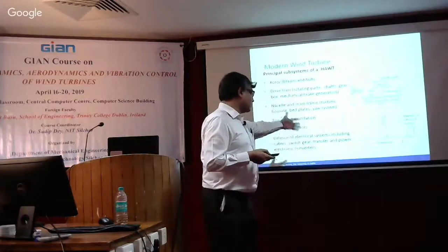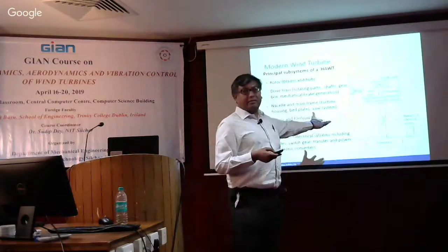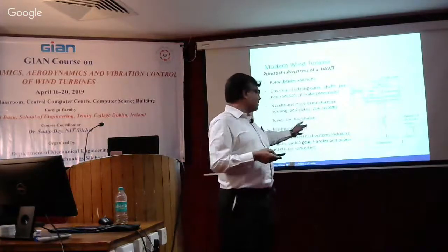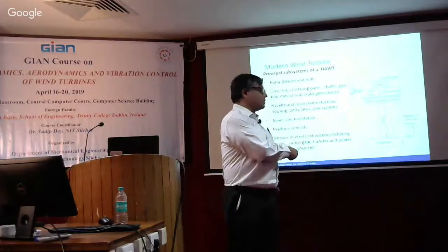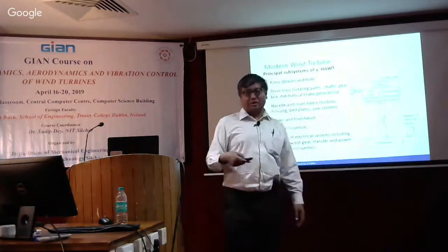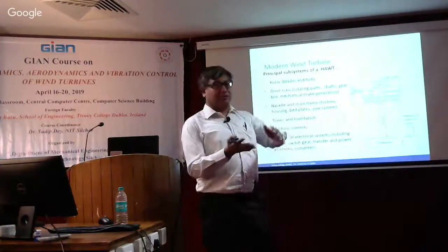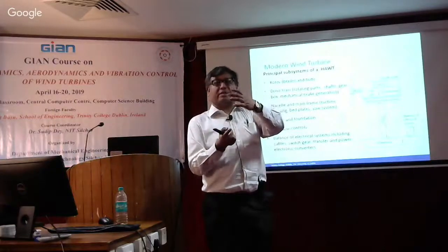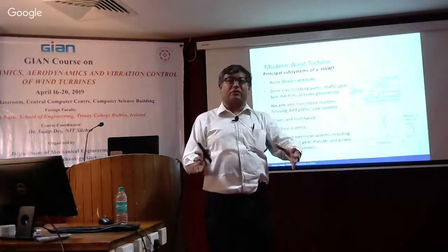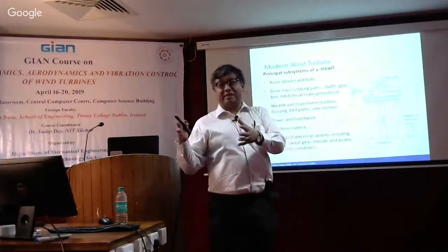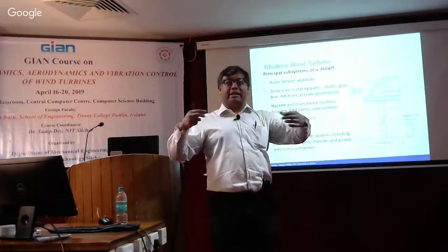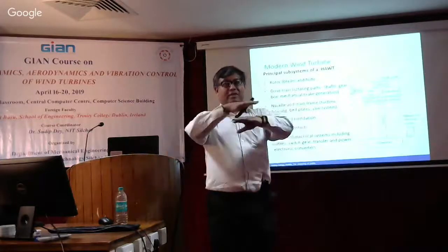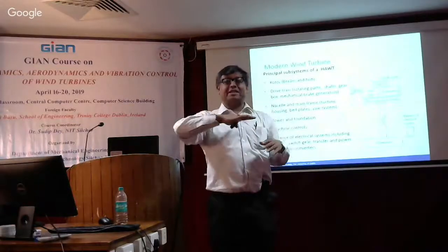And the same applies to the tower, because towers are rarely damaged. They're fairly stable structures. Once it happened, the whole thing got toppled over, but I think that was not a problem with the foundation. It was an offshore one, actually a floating turbine near shore. So there was probably a problem with the connection between the top splicing and the tower. There is a cylindrical foundation which is called a monopile, like piles in buildings, but they use much bigger steel cylindrical shells. So they're essentially shells.